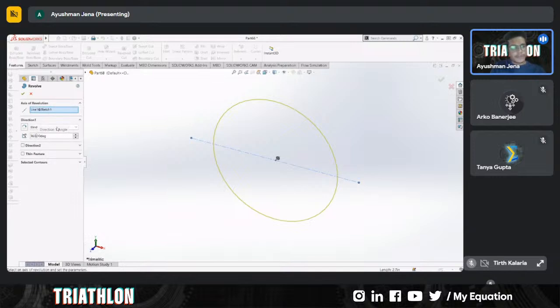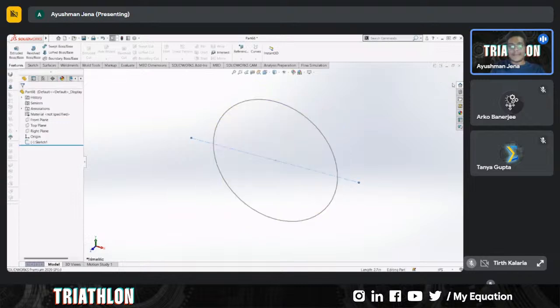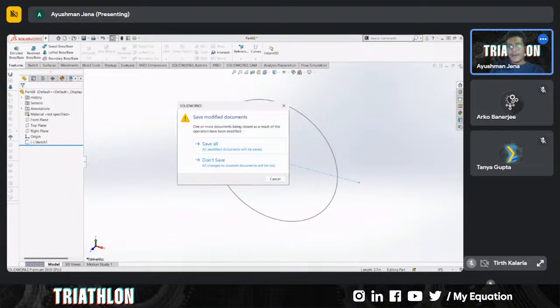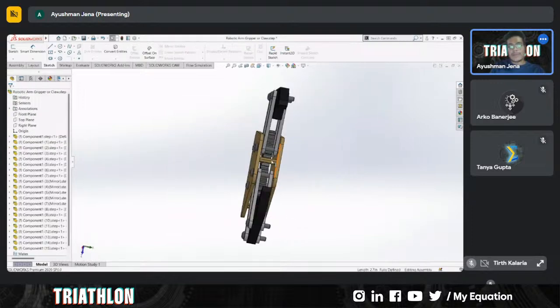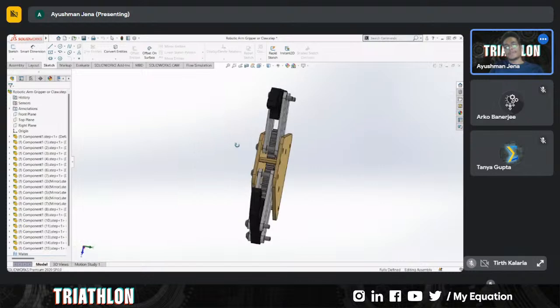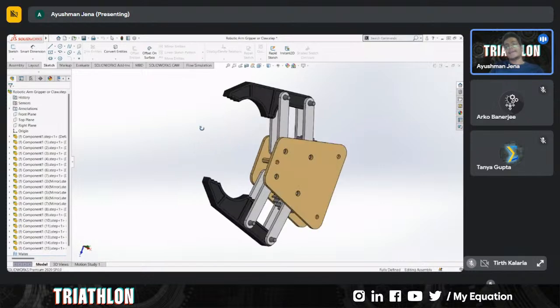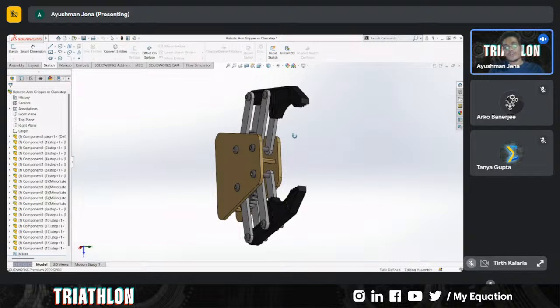So this is one of the features that you can actually try, right? So in this particular feature, we have created a sphere. Now, in order to create a hemisphere, you just rotate it 180 degrees, right? After you have created a sphere like this, you just have to add a few features. Like you can select a surface. After selecting a surface, you can create a cylinder out of it, right? So there are other features like the extrude boss and revolve boss, which can help create a lot of figures that you are looking at over here.